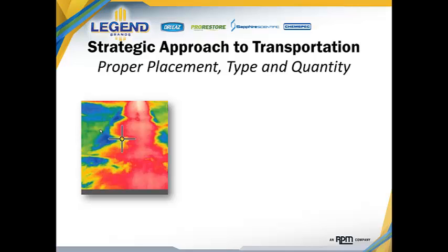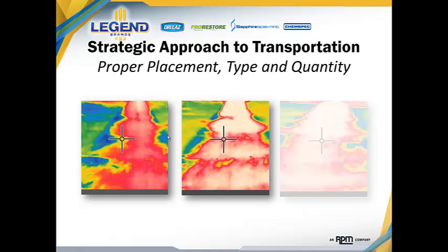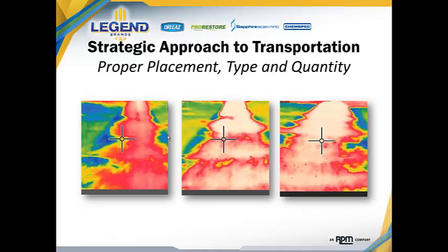Without getting into thermal imaging in any depth, just use that as a general indication of what we're looking at. As you look at different air moving technologies, one thing that you'll note is that different types of air movers have very different impacts on the drying effort. And the reason for the difference is the amount of air that the air mover places into direct contact with the surface.